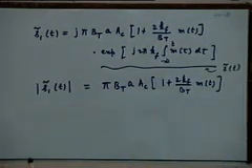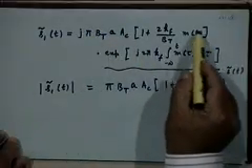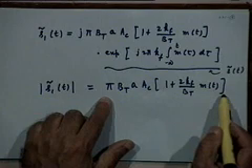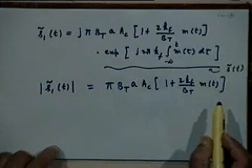However, the envelope detector is a diode followed by an RC circuit. It hardly matters whether the carrier has a constant frequency or whether the carrier phase keeps on varying. The operation of the detector is essentially based on detecting the peaks of the carrier. It tries to track the peaks, and it won't matter whether at times the cycles come close together or are slightly far away from each other. It will produce an output proportional to the instantaneous envelope, which is precisely this. So the modulus of this is equal to this, which is the envelope detector output.